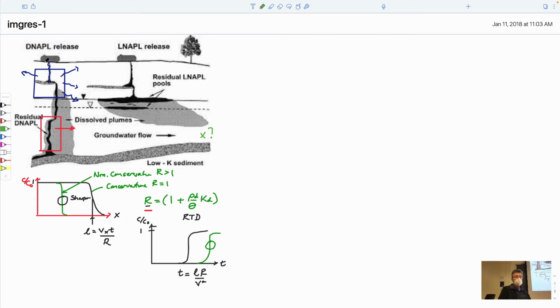So we also know that if we have a spill on the surface or in an underground storage tank, it might be above the water table. And if that is above the water table, then the processes by which transport will occur are somewhat different. We know that the chimney, as it goes down through here, will go through the vadose zone, and there'll be some off-gassing through that. If the source is present within here, then we might want to understand something about the mechanisms by which it can be transported in the predominantly gas-filled pore space of the vadose zone.